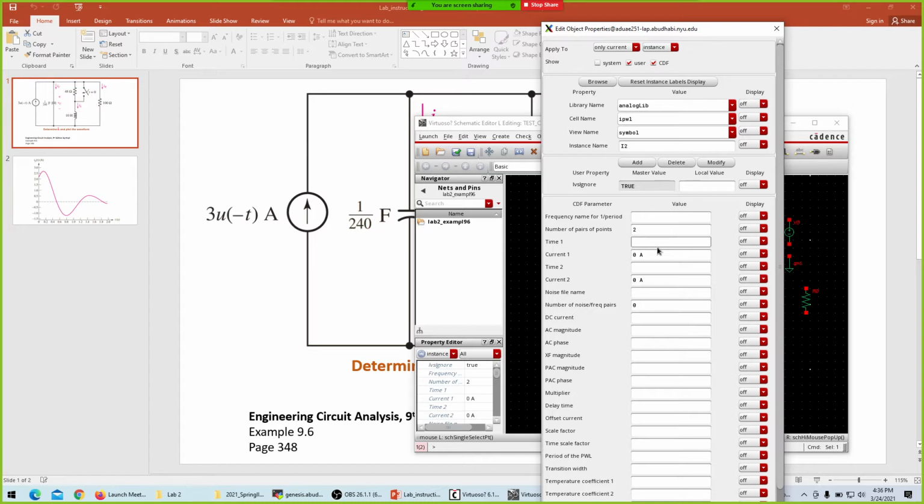So, like I explained in LTspice, I would not like to start this simulation at time 0. Instead, I'm using my time 1 second as a 0 second. So we're considering all the things happen before time 1 second, and time 1 second is our new time t, which we are considering as a 0 second.